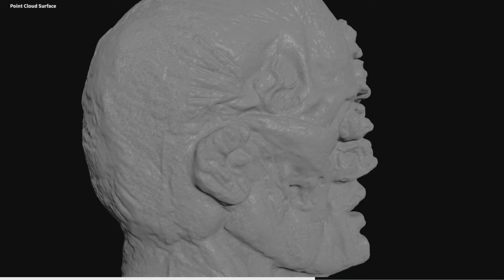The point cloud surface op does the heavy lifting of generating a polygonal surface for the points. Of course, good quality point normals are important for good surfacing results, and that is often the first thing to inspect if the surface does not match your expectations. Another important consideration when inferring a surface from points is the expected behavior at surface boundaries.